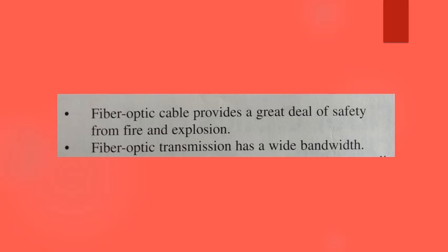Safety. Fiber optics can be installed near explosive vapors and dust, such as in petroleum factories or food processing plants. This use eliminates the fear of an electrical spark caused by a shorted or grounded circuit using conventional conductors. In addition, light for illumination can be directly transmitted through fiber optics in place of conventional lamps. When using electrical lamps for illumination in hazardous industries, the lamp fixtures must be a very expensive, explosive resistant type. Fiber optic lamps are safer and cheaper.